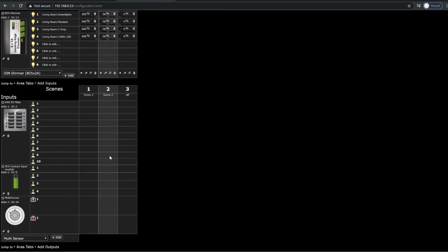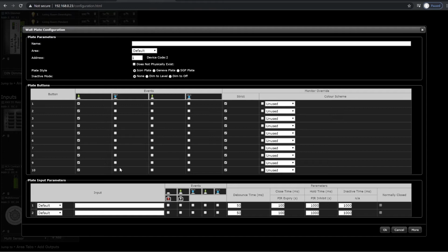So let's take a quick look at a keypad in a little bit more detail. As we can see here, we're in the spanner page for the keypad, and we have a bunch of different possible events going across here that we can open up for our keypad to give us different options. At the moment, we've just got the standard press command. So anything that happens will instantly happen on a press. The next one down would actually be only when the button is held.